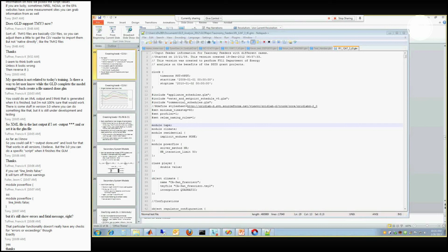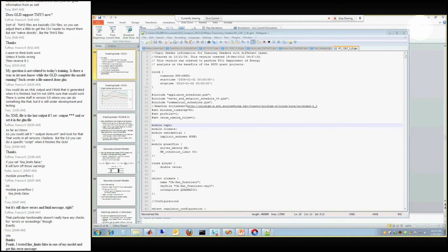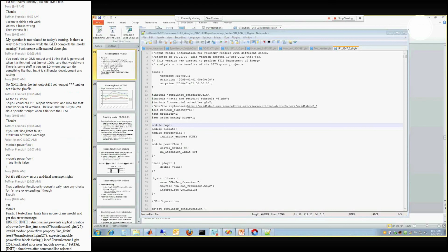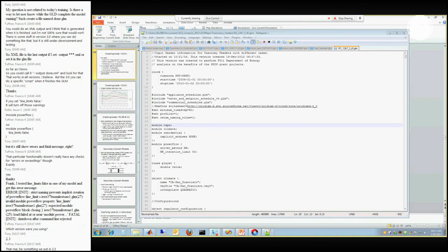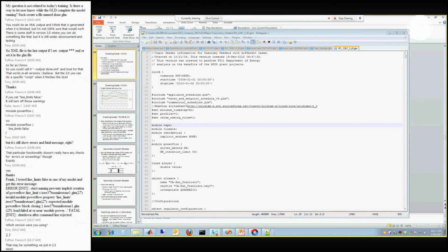Really the great thing would be if a commercial vendor came along and took it and said, oh, yeah, all this is missing, let's put in short circuit or whatever that might be. That said, the one piece we have been working on is what we're calling Delta mode, which the very first pieces of came out in 2.3, but we're really going to start coming out in 3.0 and 3.1. They're designed to look at sub-second dynamics, so sub-second machine dynamics specifically for unbalanced systems. That's where we're trying to get to that transient level of behavior. Those pieces will be filtering in over the next probably year or so, year and a half maybe.